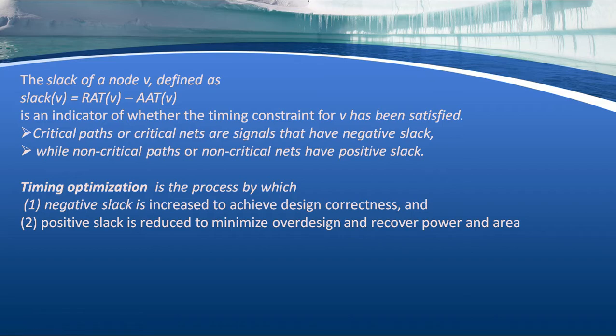See, negative slack indicates a deficiency in our circuit performance, because there is a mismatch between clock and data delay. Positive slack, when reduced, gives us the opportunity to minimize power and area and to recover them.